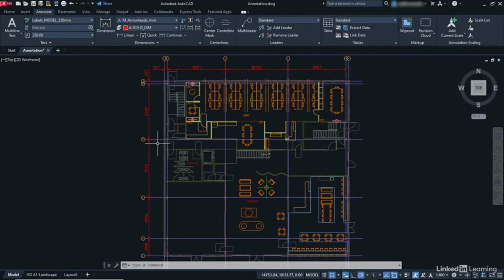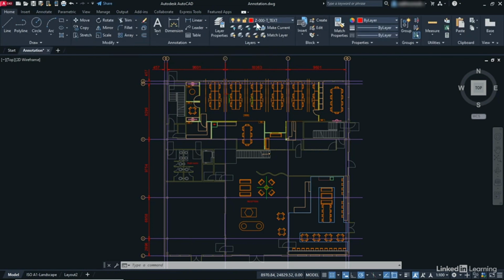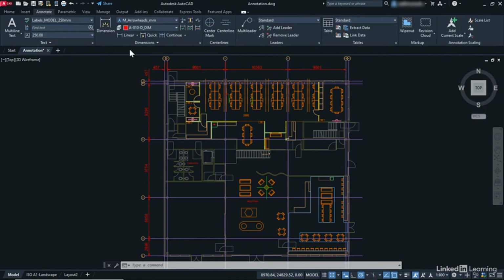But you'll also notice here in the Dimensions panel, we've got Dim Layer Override. And I've already got that set, so if I place any dimensions, it'll override my existing drafting layer in the Home tab, which is the text layer there. So in the Annotate tab, AutoCAD already knows I'm going to be using that dim layer to place any dimensions. So what we're going to do is work from the Annotate tab. Annotate tab on the ribbon, Dimensions panel here, click on the little arrow.